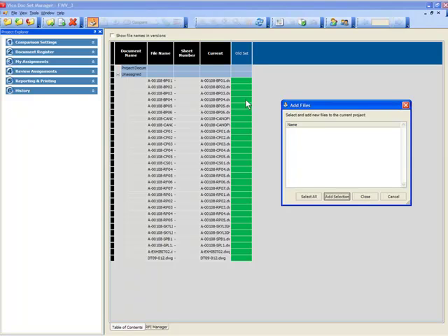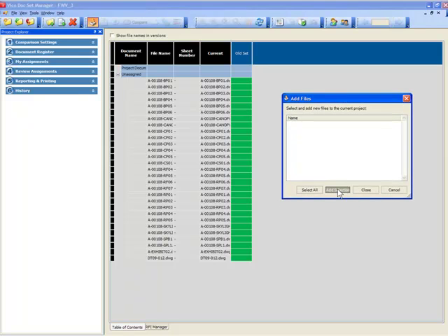What's going to happen is it's going to sync up every drawing side by side, and then it's going to scan the most obvious changes within the documents. When I say most obvious, I mean things like file size. Did they change? Well, if the file size has changed, something's changed. I don't know what, but something. Is the save as date changed? Things like that. So that's what's going to happen now. I'm going to do that. And I'll close.